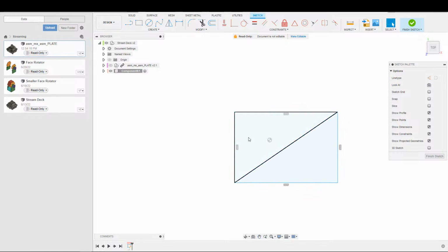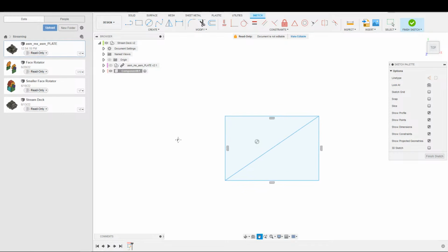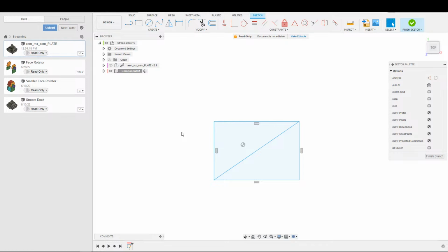In theory, I guess I should decide. Let's go with 3, 4. The question is, we've got 14 by 14 as this minimum space we need for each switch, but we want to buffer around them. So let's go for 20, I think. I'm thinking 20 should be more than sufficient as a buffer around the switch itself. 20 minus 14 is 6, which would be 3 millimeters on each side. Yeah, that sounds safe.